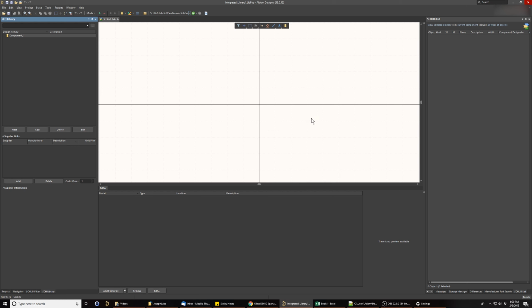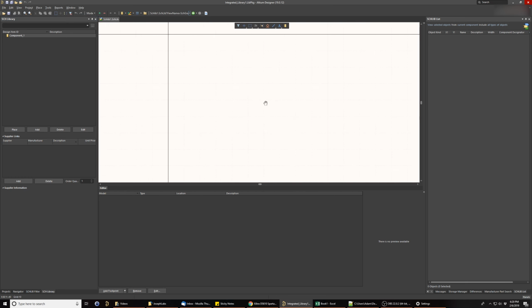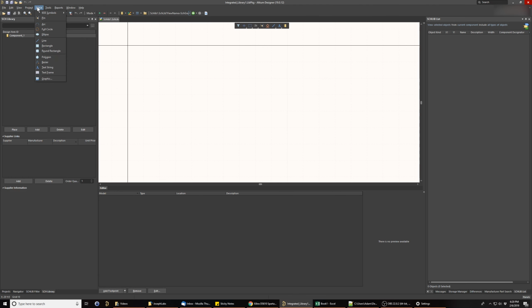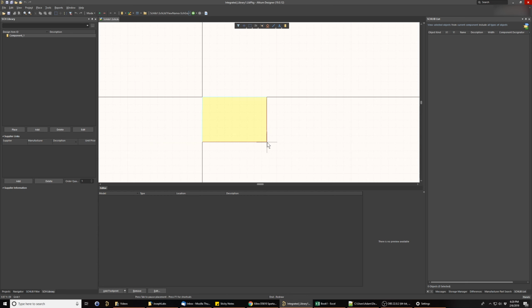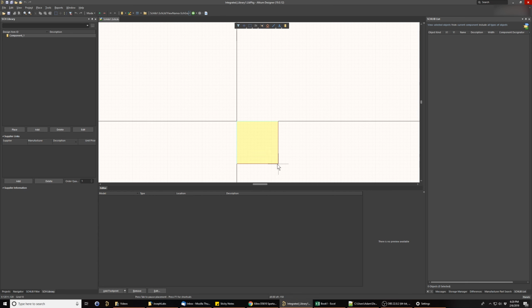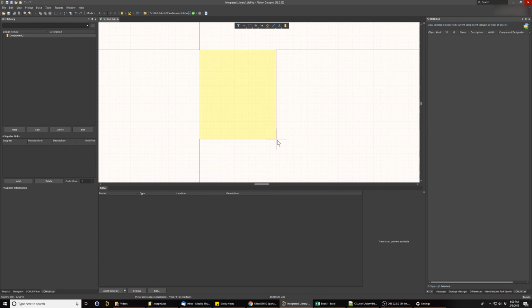What you would typically do to create a regular IC component is place a rectangle for the body of the component by going to Place, Rectangle, or the hotkey PR, and then size the rectangle and add all of the pins manually one by one. In this example, it would probably take a decent engineer a couple of days to complete this component while ensuring there are no errors.